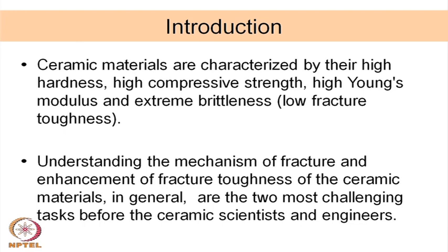Well, to start with, as all of us know, ceramic materials are characterized by their high hardness, high compressive strength, high Young's modulus, and of course, the most characteristic feature of ceramic materials so far as the mechanical property is concerned is extreme brittleness, or in other words we also talk about low fracture toughness or even low toughness sometimes.